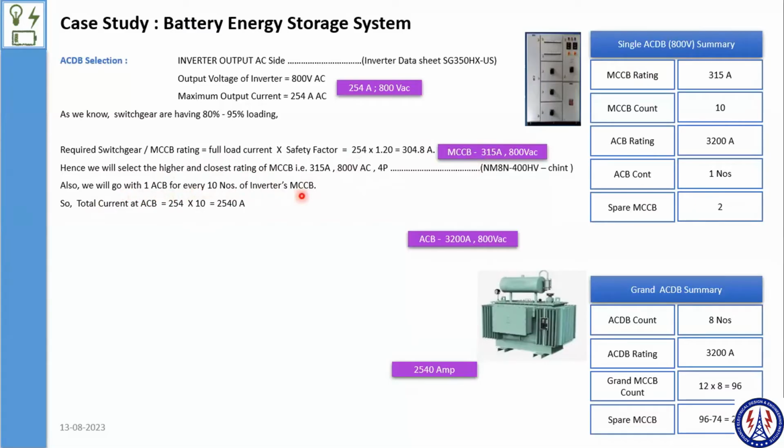This is the panel which you need to plan and club. How many inverters you want to club in a single, let's say, ACDB is your choice. It's a designer perspective. I thought here I can go with, let's say, 1 ACB with 10 inverters. So if I look at the 10 inverters, the capacity would be 3.5 megawatt, and that is good enough.